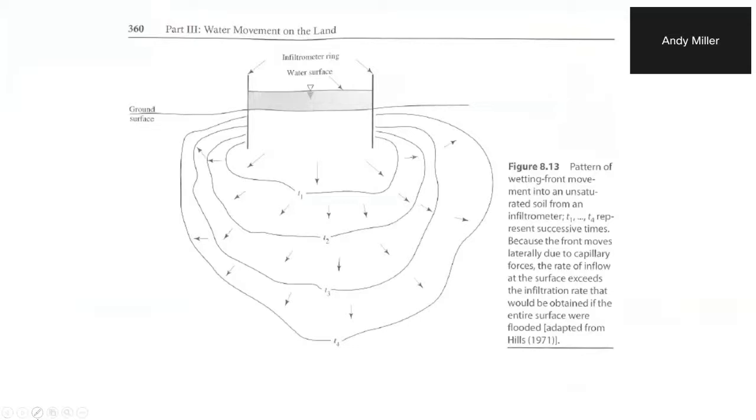Now, the thing that's interesting about this is, if you're seeking to measure the rate of infiltration, thinking in a one-dimensional fashion about the vertical transfer downward, what's the problem here? How is this going to perhaps frustrate your expectations of getting a good measure of vertical downward transport? You have horizontal transport. Yeah, horizontal transport. Why? Because it's going against the equipotential lines. It's going to flow out and back up.